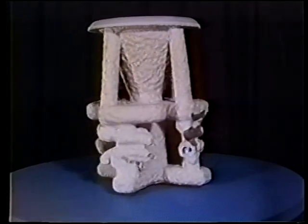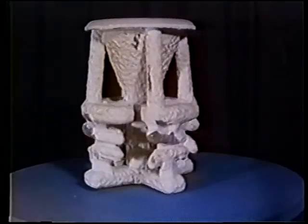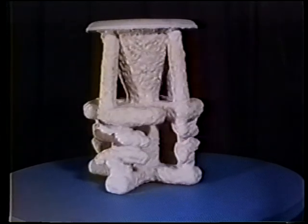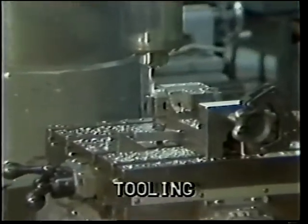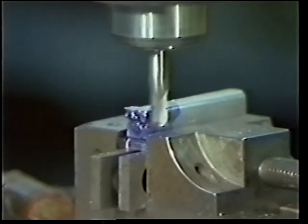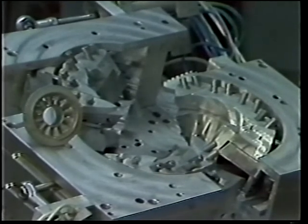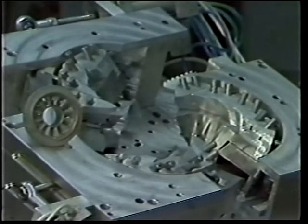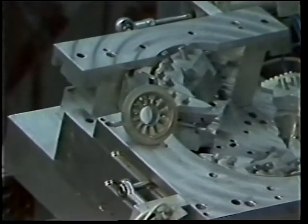Investment casting uses a mold produced by surrounding an expendable pattern with a heat-resistant ceramic material. The first step is the production of a master pattern die. Here, a special automated die for a combustor swirler is being machined. Investment casting dies are usually made from low melting point metal or from steel. When steel is used, the cavity is usually machined directly in the die. If low melting point metals are used, the dies are cast using a master pattern.